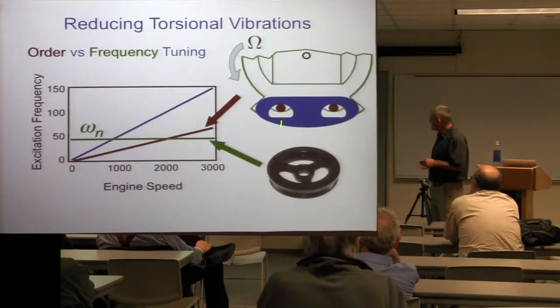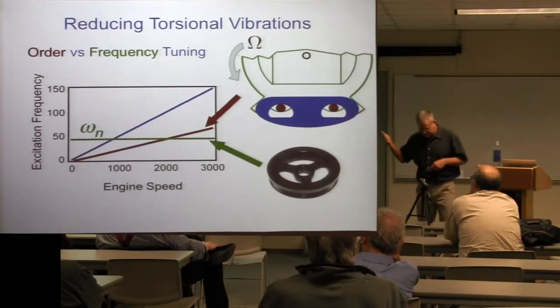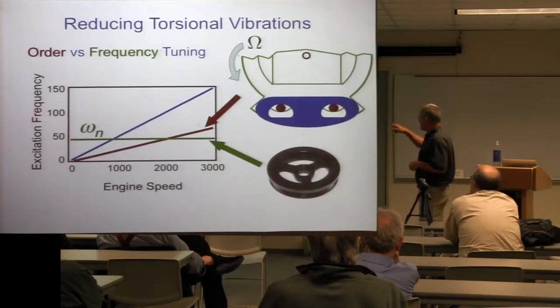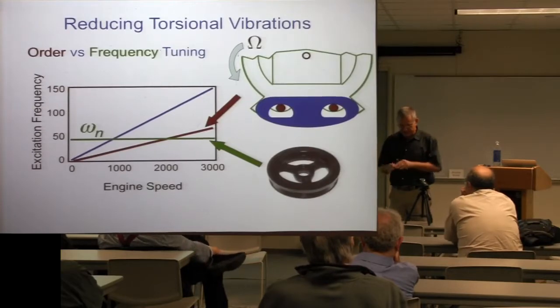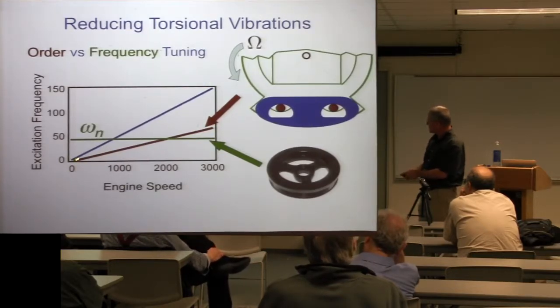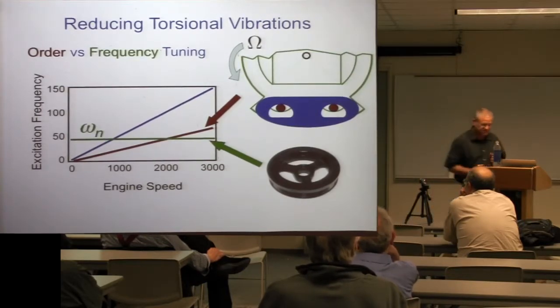And these are two pins that ride on these green rollers relative to the crankshaft, and these surfaces, so the center of mass follows a path. The beauty of this, and the key difference between this and a regular tuned absorber I talked about, is that this is driven by centrifugal effects, which in its natural frequency scales like the engine speed. So if you think about that torque that was n times theta, well, if theta is roughly omega t, that means the driving frequency scales with engine speed, and so you can tune this absorber so that it scales. If you line these two lines up, this thing stays tuned at all engine speeds, whereas these harmonic balancers are essentially mass spring systems.